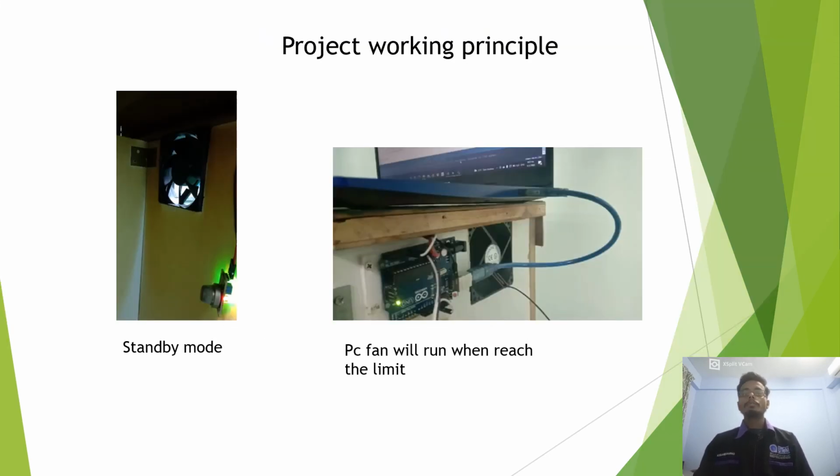And now I'm going to explain how the project will be working. At first, when the system is powered, the PC fan and also the sensor will be in standby mode. And once the ppm value increases in the partition, the exhaust fan, which is fixed as the PC fan, will start running to extract the unwanted gas in the partition.